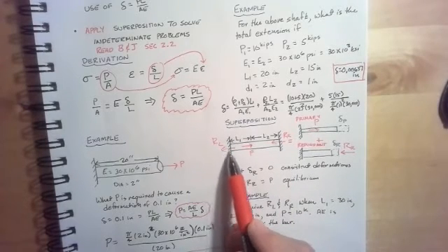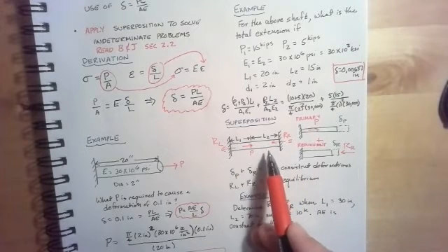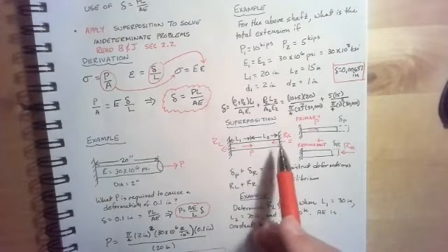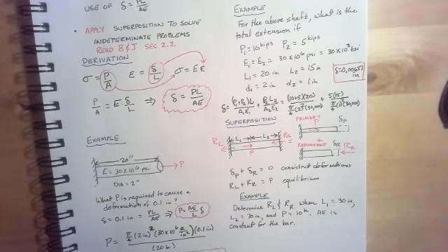And in this case, we have a support reaction at the left fixed support and at the right fixed support. We only have one useful equation of equilibrium that says the summation of forces in the x direction equals 0. So how do we handle a problem like that? We know it has to obey all of the principles of statics, but there are an infinite number of combinations of the left and the right reaction that would add up to P.